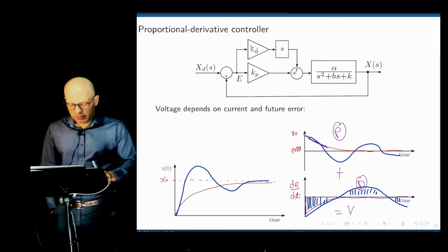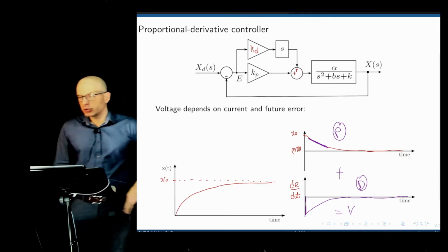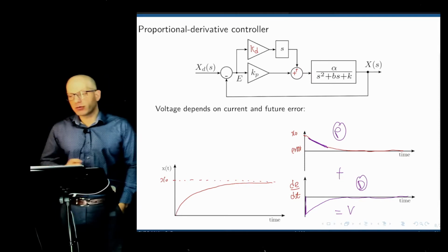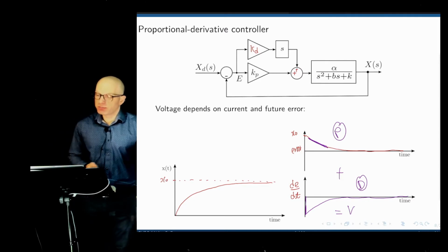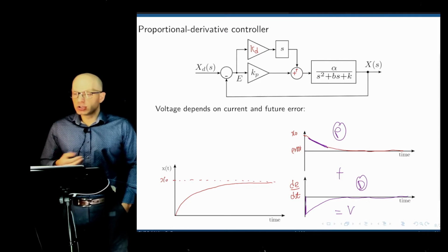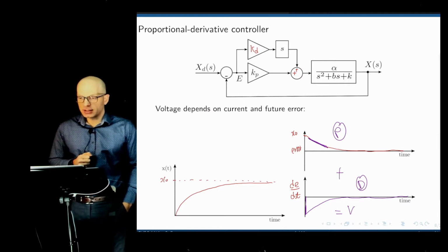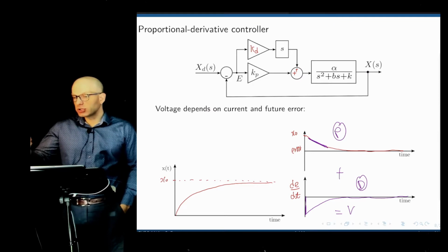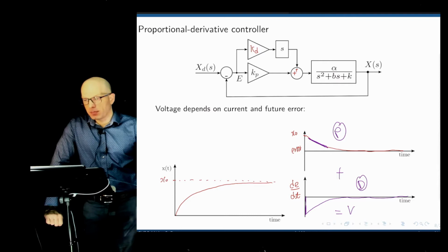And that's the idea behind the derivative controller. We could say, it's a bit of a stretch here, but we could say the derivative controller is predicting the future behavior of the system and then taking action before that takes place. It's looking at the rate of change. It's looking at how the system will be a few seconds ahead, if you're going towards the destination or not. And then based on that, we adjust the gain. We adjust the control action based on that, right?